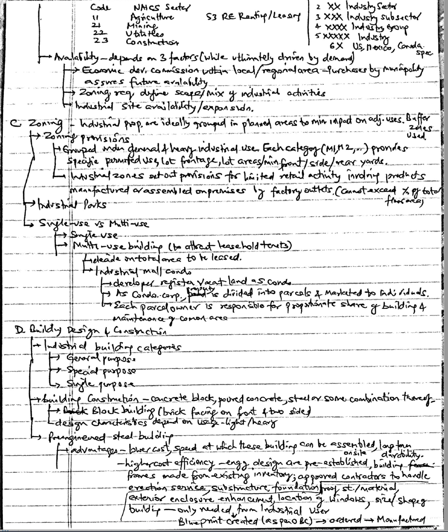Built-up roof life is dependent on many factors such as weather conditions, quality of material used, number of plies installed, and the amount of roof foot traffic. A properly installed high-quality four-ply roof should last 15 to 20 years.